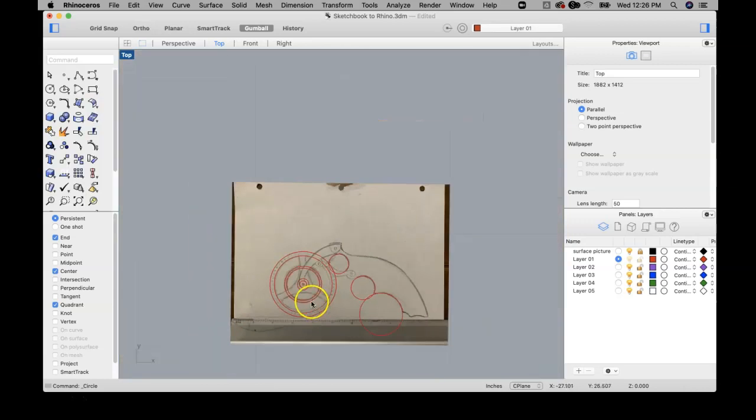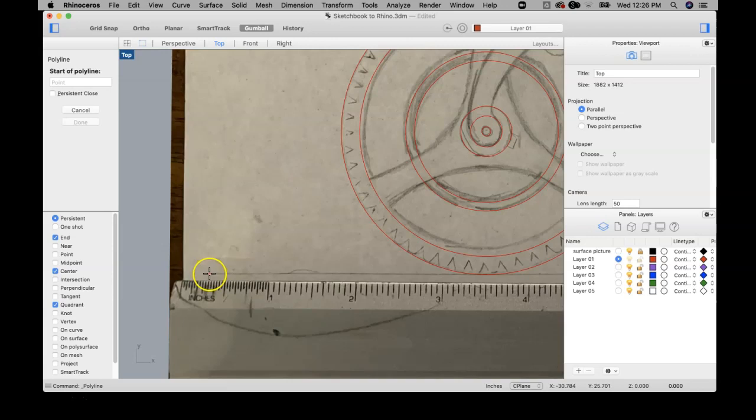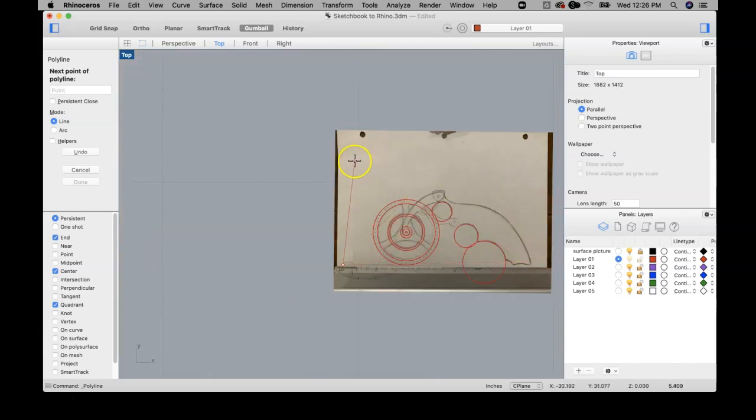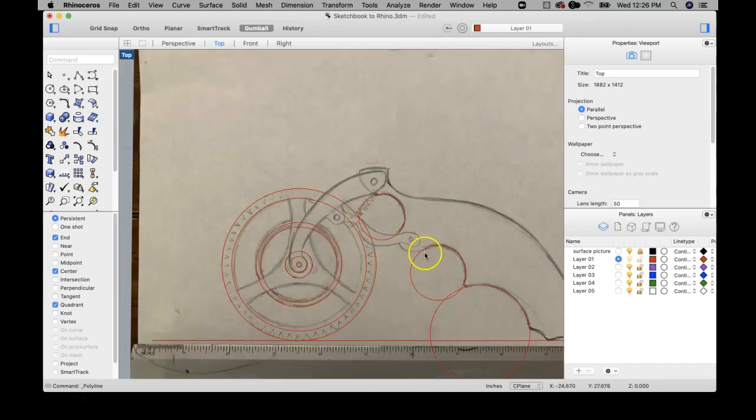Sometimes I'll put in a ground line that represents that line I drew, which is here. I'm going to show you a little trick with this. If I want to hold this line straight, I just hold down shift, and you'll notice it locks it. Shifting for the second point will either, if I'm closer to the vertical, lock it vertical. If I'm closer to the horizontal, it'll lock it horizontal. And then I can click there.